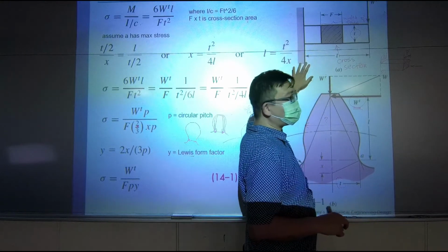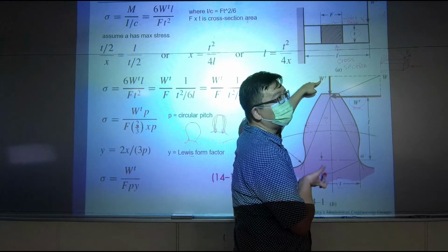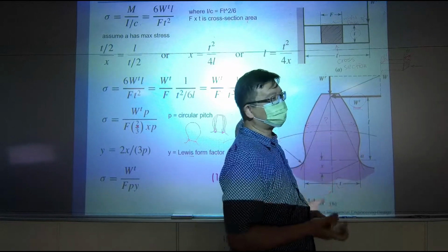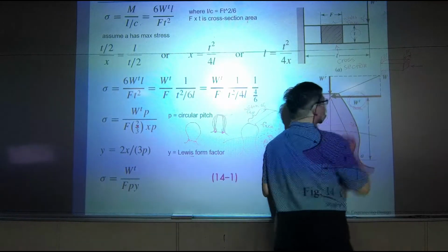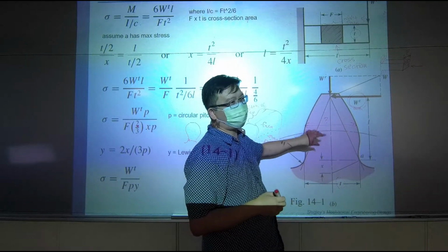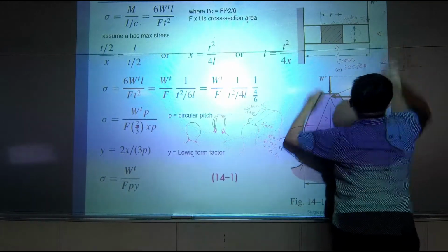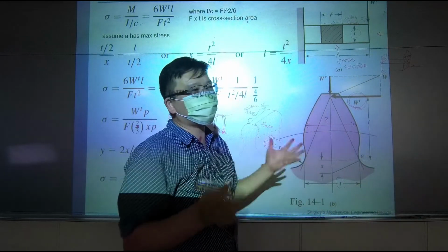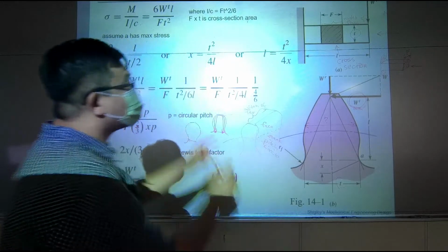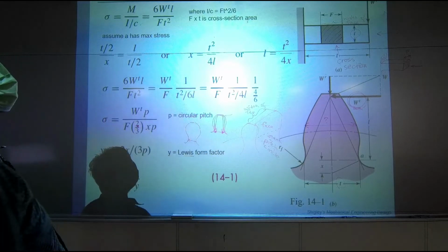And you never see a tooth being crushed by this force. You only see a tooth being bent and break. So the transverse force is more important for force analysis of the tooth. That's why in this model, they don't even care about the force along the other direction. That doesn't break the material.